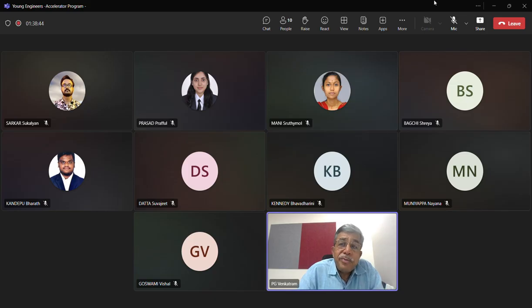Most of our columns will be proportioned so that they will not buckle, because buckling is an instability problem and we want to avoid that. So it is extremely stiff, which means what? In the vertical direction, your response spectrum will always land in the small natural period zone, which means the highest Sa/g. And that value can be very significant, right?